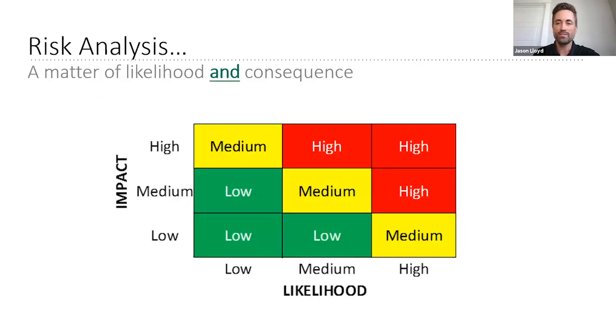First, the definition of risk to ensure we're all on the same page. Risk is the product of likelihood and consequence. A high or significant consequence with a very low likelihood renders a low risk scenario. On the contrary, high likelihood along with significant impact renders a high risk scenario. We'll be discussing the balance of these variables of risk throughout this discussion, but I need us to keep in mind that in these new AASHTO guide specifications that I'm going to explain later, we are conservatively ignoring how likely something is to happen, and instead we assume in the analyses that it's already happened, no matter how unlikely it actually is, and then we analyze for the consequences.